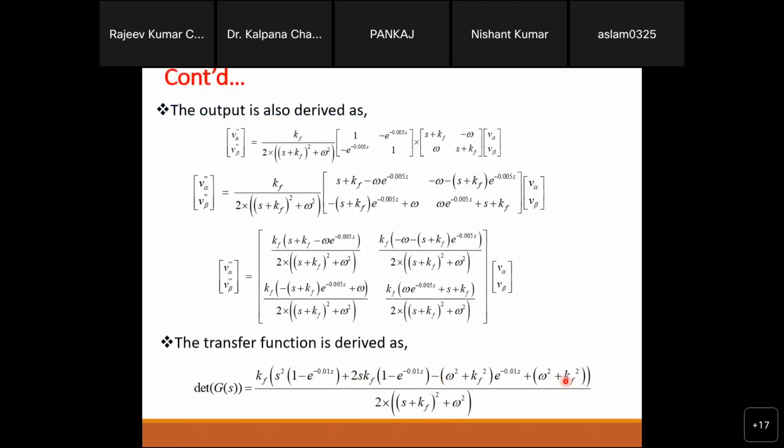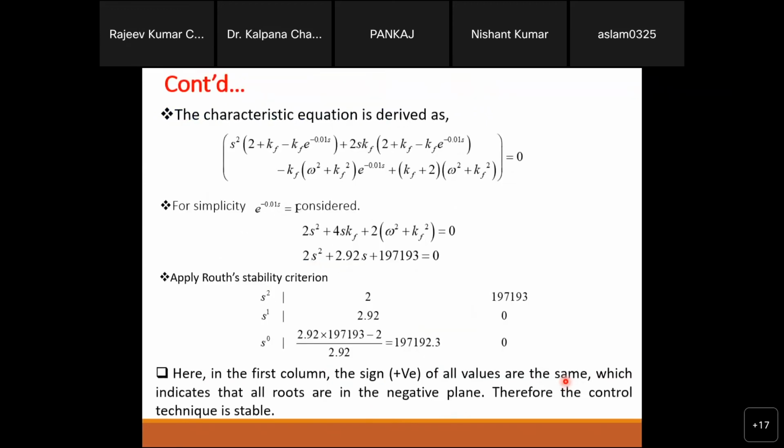Omega is frequency. After that we can use the Routh-Hurwitz stability criteria. With the open loop transfer function G(s), and after that if we have this 1 plus G(s) equal to 0, we can use the Routh-Hurwitz stability criteria. So this is the Routh-Hurwitz array, with the s powers 2, 1 and 0 and like that. Here what we have done, I put in the omega value here, and then rewrite those equations. The equations will look like this one, and then you will see this one.